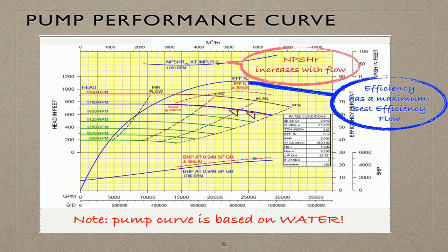Regarding the efficiency curve, since the power gained by the flow is different from the power received from the pump, we have this diagram and curve due to different types of losses. There is an operating point in a pump where the efficiency is maximum, and it is known as the best efficiency point.